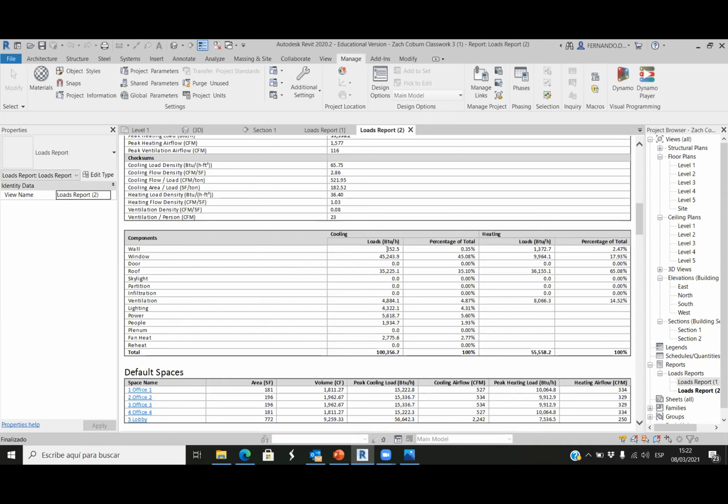Second, we are losing energy through the walls, through the windows, and through the roofs. What is the worst part? The window. It's always the worst. In cooling, the window is terrible. In heating, it's not that bad because we have used triple glazing. That's fine. But the next thing we have to change is the roof. So probably I would add more thermal insulation on the roof. It's fine. R80 is a good value. It meets the passive house standards. But can we make it better?